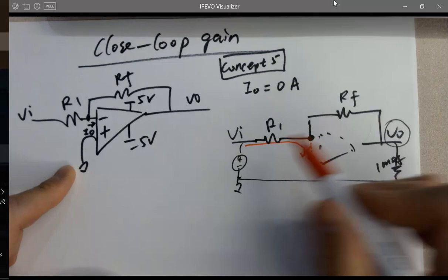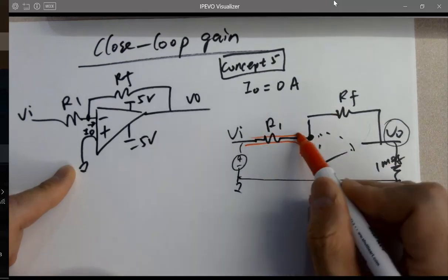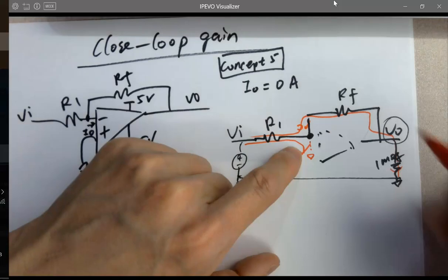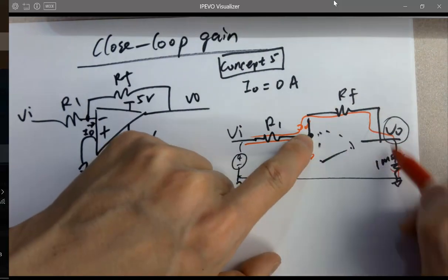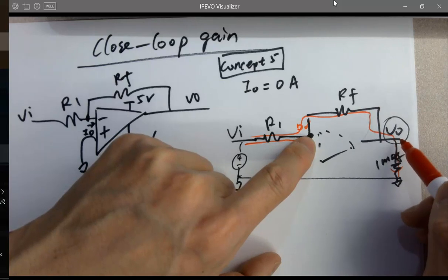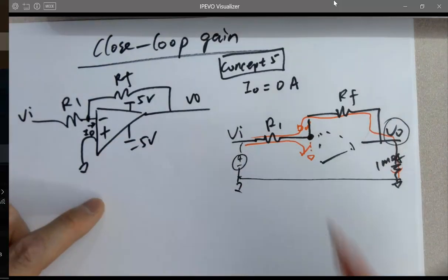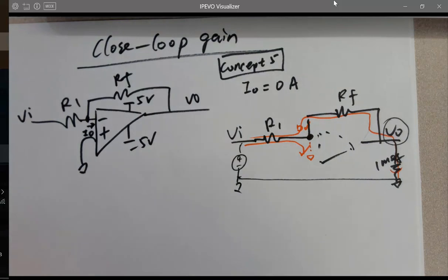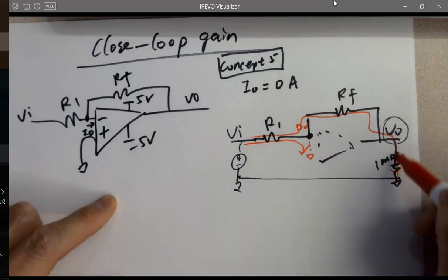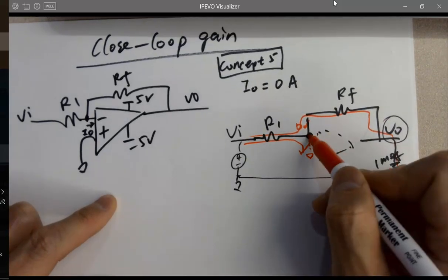And then because this is a resistor network, it's going to keep flowing to here. You've got 0 volts here, and the current flows that way. So it's actually boosting VL if you drop it really quickly to ground first. It's changing the phase, but it's actually increasing the voltage. That's the only way you can do it. You have to drop it to 0 first.